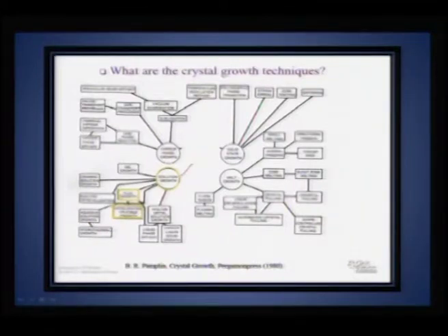So apart from solution growth that we have seen so far, the other important way of realizing crystal growth is through vapor phase growth. In module 2 I have already discussed the most sophisticated vapor phase technique, which is molecular beam epitaxy, and I have also mentioned general vapor evaporation, chemical vapor deposition techniques, and vapor phase epitaxy.